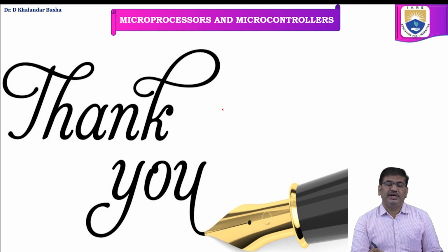Thank you. So in this session, we have discussed programs related to the 8051 microcontroller. In the first problem statement, we discussed how to configure the TH1 value for various baud rates like 9600, 4800, 2400 and 1200. Later, we have seen two programs for transmitting a single character, followed by transmitting multiple different characters. The last program is about receiving data using serial communication of the 8051 microcontroller.